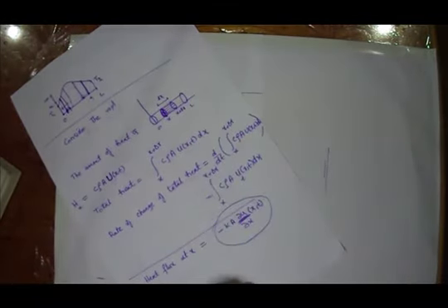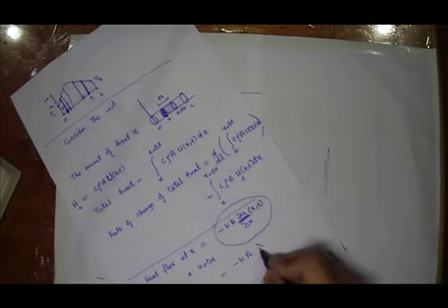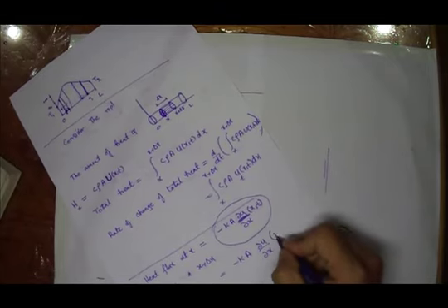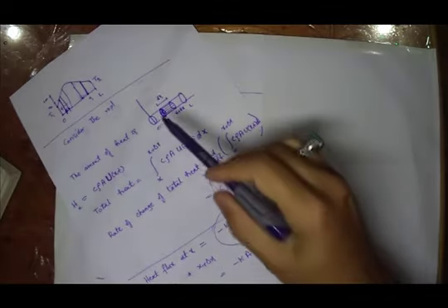Similarly, we can also analyze the flux at the other point, the heat flux at x plus delta x. This is equivalent to minus k a partial u over partial x at (x plus del x, t). These are basically the flux at these 2 points.